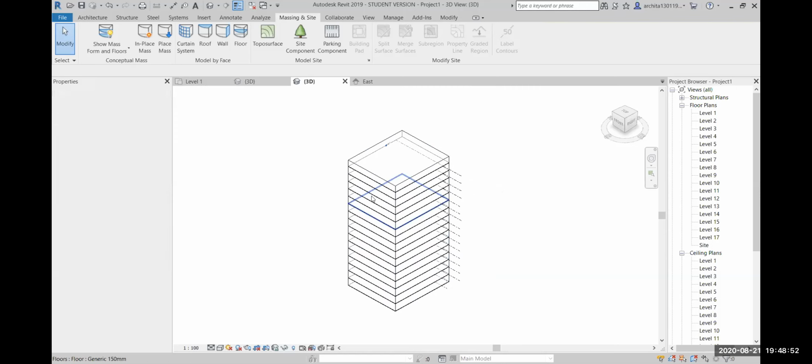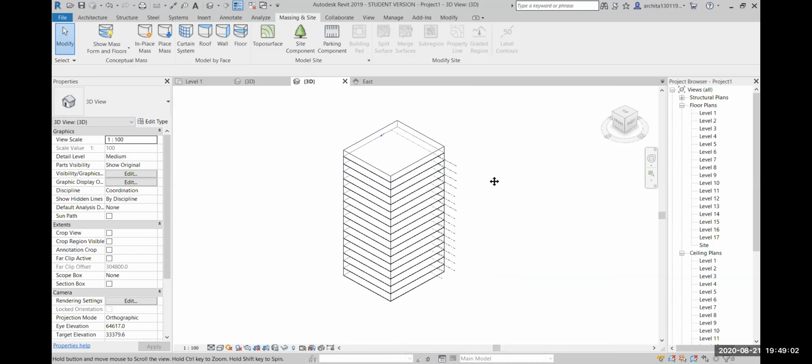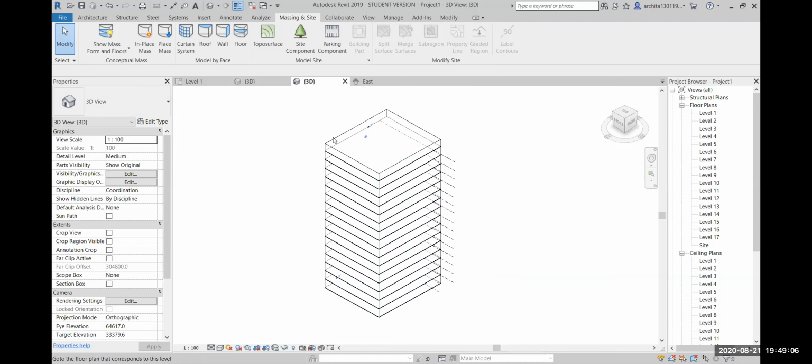So I think till here we all learned, right? We didn't go any further to wall and roof. No, ma'am. Okay. So now, just like very easily we can create the floors, we can also create the wall and the roof. So go to Wall by Face. That means it takes the mass face and creates the wall by clicking on the walls.